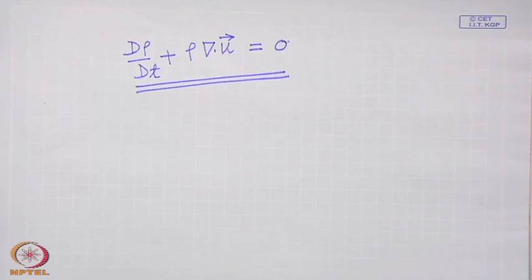Remember this very clearly. Density is not constant. It says the density is independent of pressure. An incompressible flow is defined when density is independent of pressure, not that density is constant. A constant density is not an essential requirement of incompressible flow. Density may change in incompressible flow.